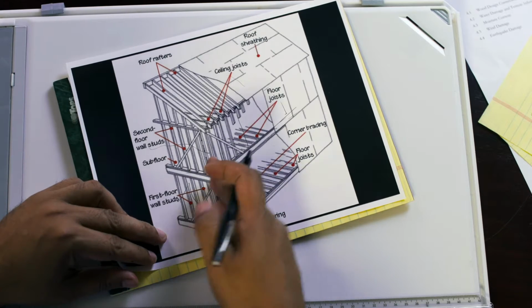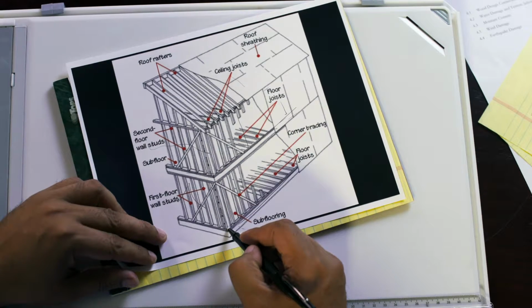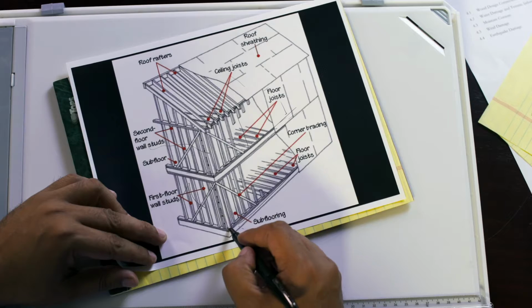So there's a limit on how far you can make a tall column. And this is important for architects to understand, that you can't design a complete column that's going to span from the base of the foundation all the way up 40 feet. I mean, it's unrealistic. And I've seen designs like that happen, and it's not possible. You have to remember that you have engineering limitations on your materials.